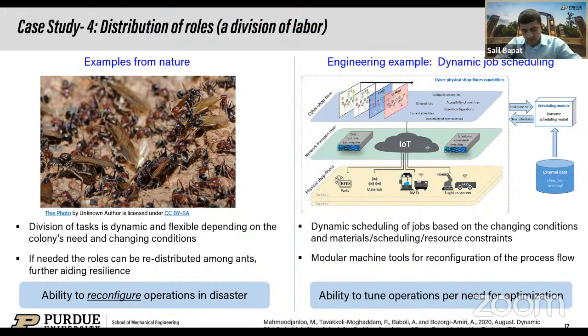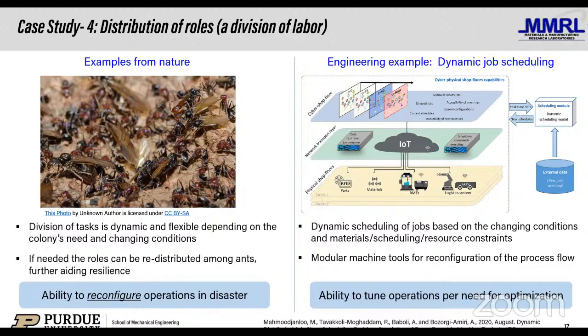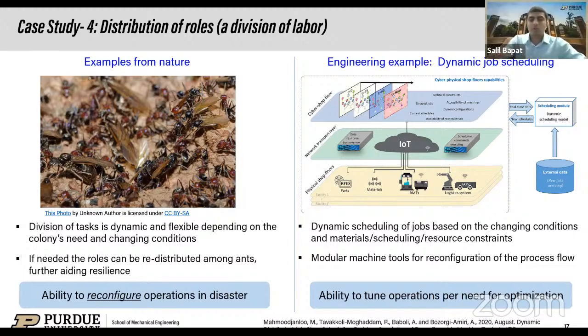Right. So just to bring it more forward, say you have a metal 3D printer. That metal 3D printer does not necessarily print polymer. So if you want to have dynamic job scheduling and now print a polymeric system, you need to completely change the printer, or go to a different printer. Whereas in a conversion manufacturing setup, you would have the same platform, the same one device, that is able, using some reconfigurable tools, to configure itself so that it can now print polymer using the same system.